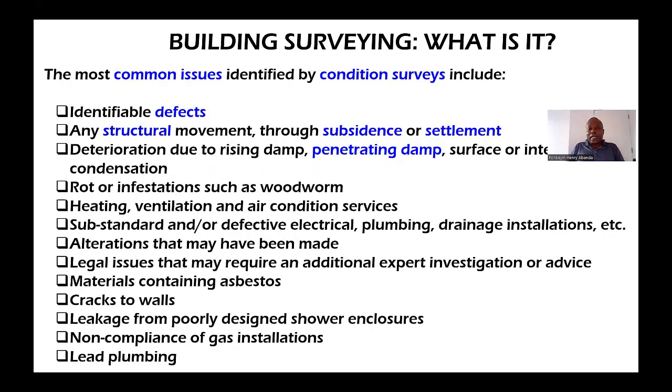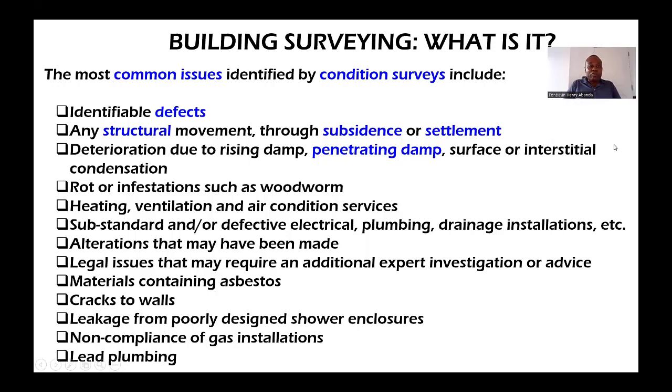The most common issues identified by condition surveys include defects, any structural movement through subsidence and settlement, deterioration due to rising damp, penetrating damp, surface and interstitial condensation, rot infestations such as woodworm. I won't spend time reading all of those. Some of that is obvious, and you can read them in your own time.